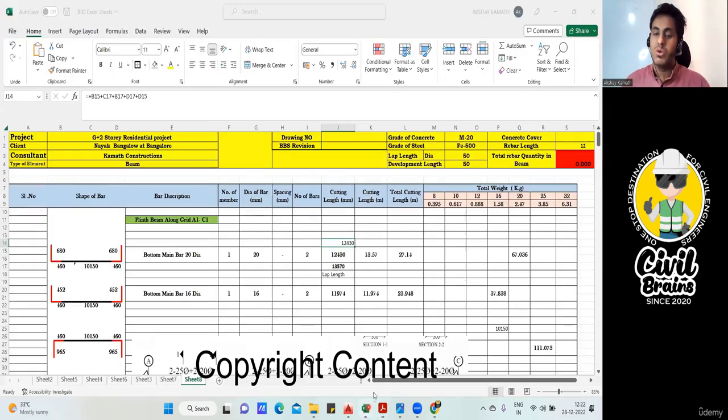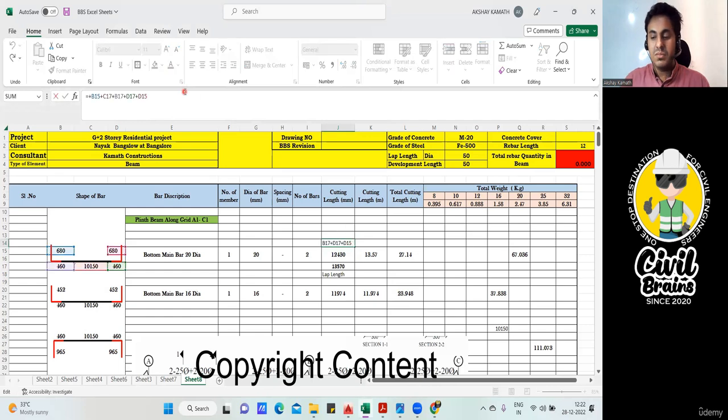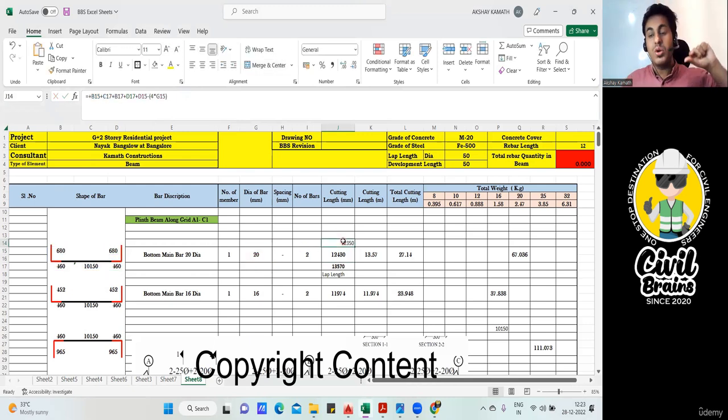But again, I always repeat, if your company is following that, and after doing that also you are supposed to apply the bend deduction, you're free to do that. Come here, minus, open the bracket. How many bend deductions will you do? 90 degree I'm getting here, another 90 degree, so two 90 degrees. For 90 degree, if it is 2D, for two it will be 2 into 2, 4D. So minus 4 into the diameter of the bar, 20, and close the bracket. This will be a cutting length according to what your company follows. But usually when we take the development length directly, which is given in the formula 57 times the diameter of the bar, you don't have to apply bend deduction. But if a company does that, or if your senior says that, or if you feel that method is correct, you can do that. You're free to do that. But I won't be doing it, so I'll delete that.